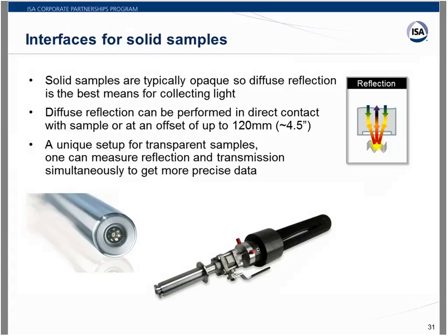And this you can work either contact, which means that you can take this probe and jab it into incoming samples to measure water content, or you can have something set up on a conveyor belt and have a distance measurement that allows you to take the reflection off of a conveyor belt of potentially like grains going through,